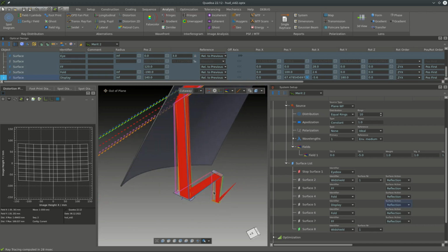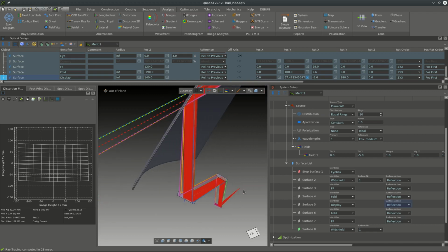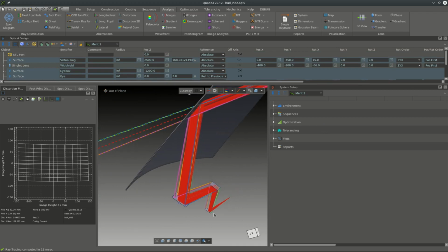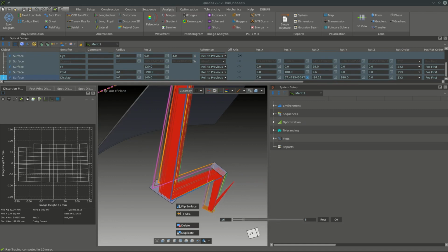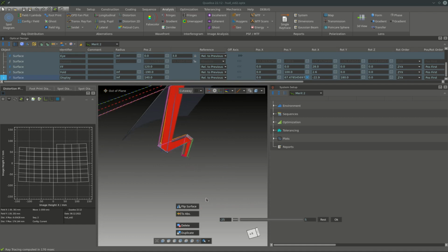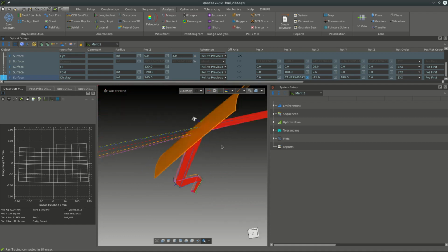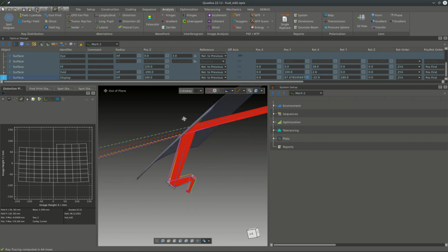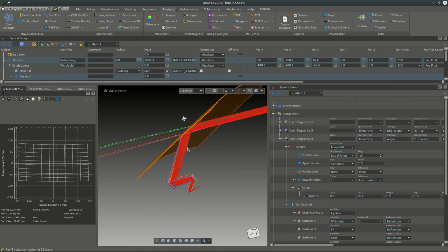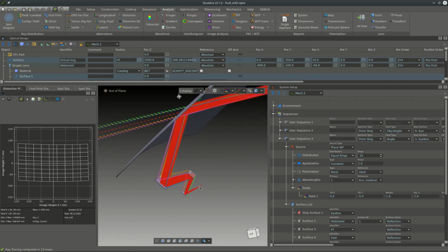And as we can see now, the light here is just reflected there and it doesn't get any further. However, if the display wouldn't have been tilted in the design at the beginning, then we could see that if we just rotate it back, we could get these rays going through up to the windshield, and this would allow a path where the sunlight can get from the sun over here, over the mirror, to the driver's eyes. However, as we can see in our design, this is not possible because the reflection will just go here and will be dumped into the housing.